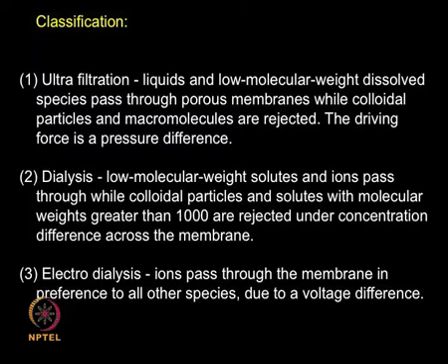Dialysis, there are membranes where again low molecular weight solids and ions pass through in a dialysis membrane, where colloidal particles, solutes with molecular weight larger than 1000 are rejected. So dialysis works on concentration difference across the membrane. So you have large concentration on one side, you have low concentration on another side. So the solute travels from the large concentration down to the low concentration.